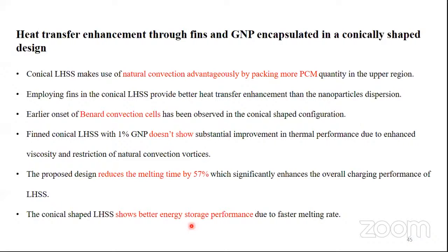Now coming to the last one, the proposed design definitely reduces the melting time, which we have proposed over here, by 57%, which is significantly enhancing the overall charging performance of the latent heat thermal energy storage system. Now the conical shaped latent heat thermal energy storage system shows better energy performance due to faster melting rate.